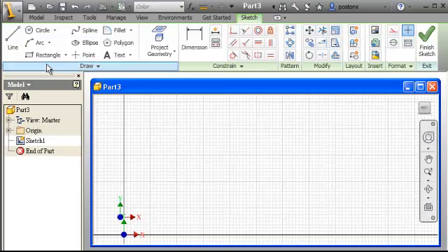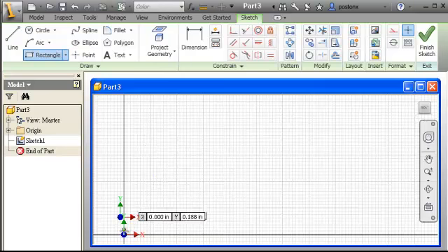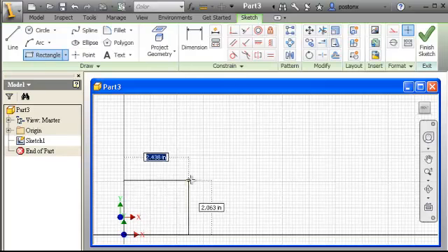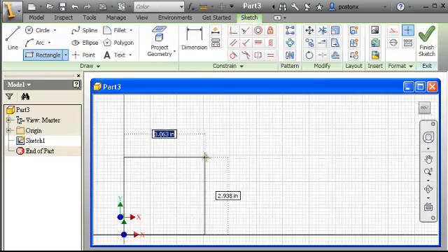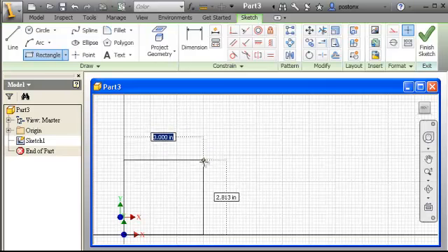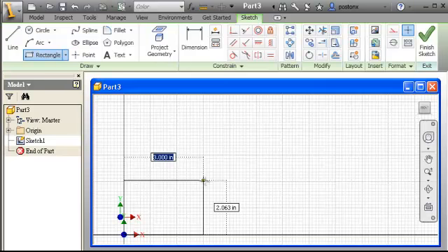So now our part, we need to get rectangular to start with because our part's a square block of steel. We're going to whittle this out. Okay, there we can see our plus sign, our little yellow dot, but when we turn down there, it turns green. That means it's hit dead nuts. It is right on the money, 3 decimal places. Okay, we need to go over 3 and up 2. There's 3, and there's 2.